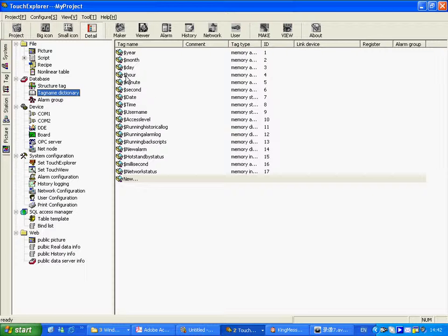The basic tags can be classified into memory tags and I/O tags. I/O tags exchange data between KingView and devices or other application programs. They are bidirectional and dynamic. When KingView is running, any change in the I/O tag is automatically written to the external device or the application program, and vice versa. The data gathered from the I/O device or instructions sent to an I/O device, such as a reactor depth and power switch, must be set as I/O tags.